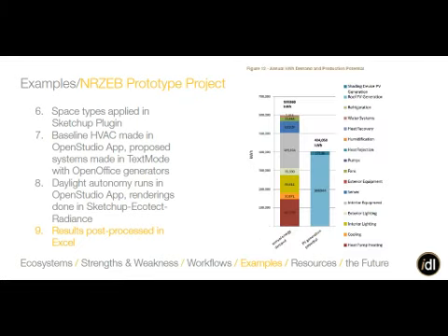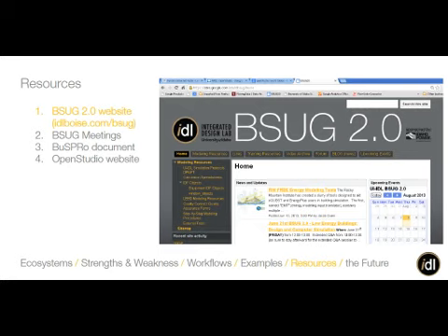We're also able to get from the model the energy demand in kWh of all these components. And then we were able to calculate with PVWatts how much they could produce on site if they plastered their entire roof with PV and also put it on the shading devices. And you can see they were close. So we did some more back and forth with them to try to manage that discrepancy.